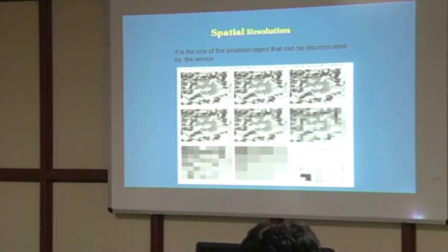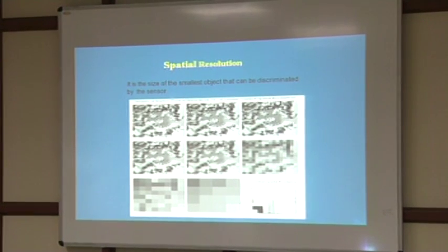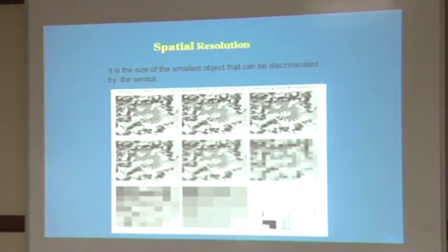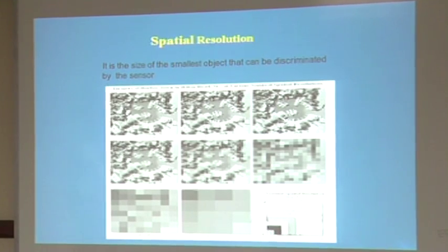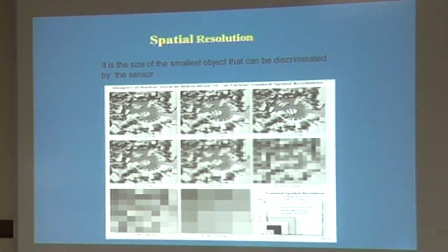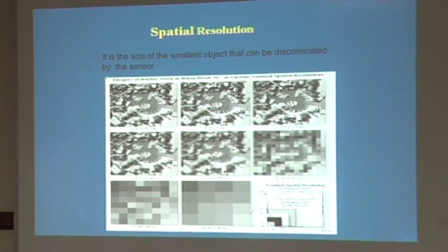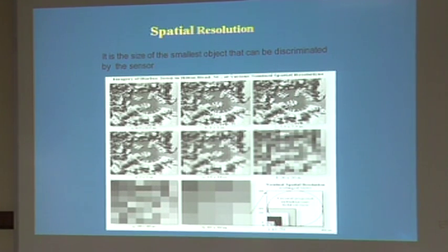So if you are using, that is the swath width, you know that the NOAA satellite has a swath of 3000 kilometers and a resolution of 1.1 kilometers, that is 1000 meters. So you may not be able to see all the objects. A 1 kilometer object will be a point. Whereas with 1 meter IKONOS, you will get a clear vision of those objects. So that is clearly explained. From this you can find out the meaning of spatial resolution.